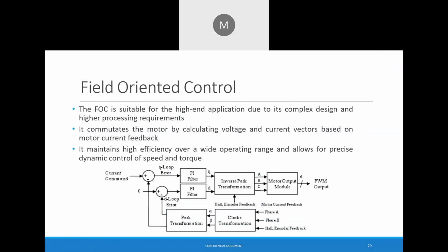Next comes field oriented control. It is a kind of sinusoidal waveform control, but the FOC is suitable for high-end applications due to its complex design and higher processing requirements. So what we discussed yesterday, integrated electronics, again comes into the picture. You need very high-end and reliable components, FETs, IGBTs.